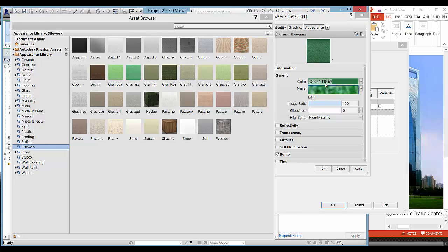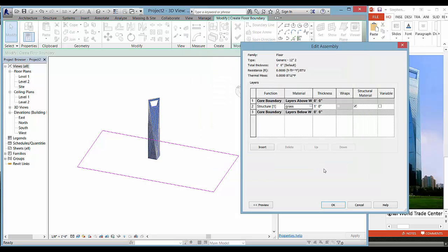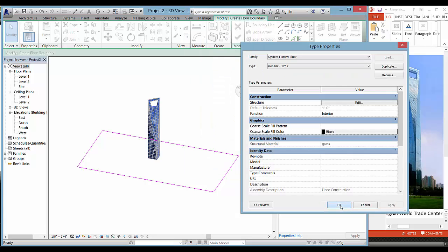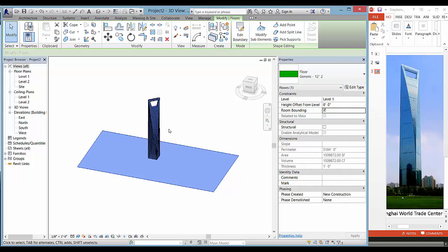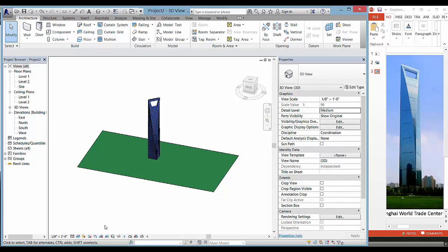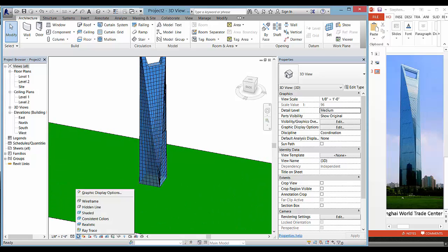Double click on it, and then you can close out of these dialog boxes. Apply it. You can change a lot of properties there too, but I just went ahead and picked OK, and then I picked the green check mark because I was changing the floor. And there's your color, a little different in the shaded and realistic views, depending on what you used for your color.